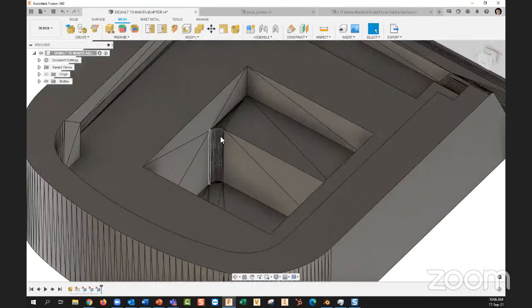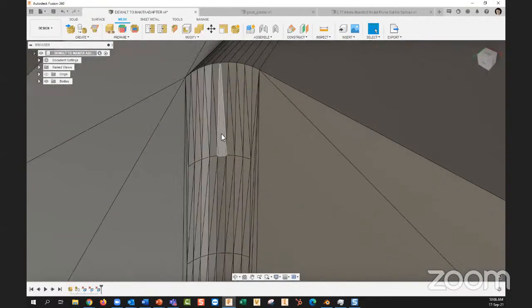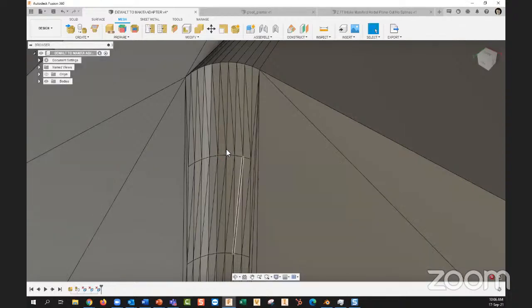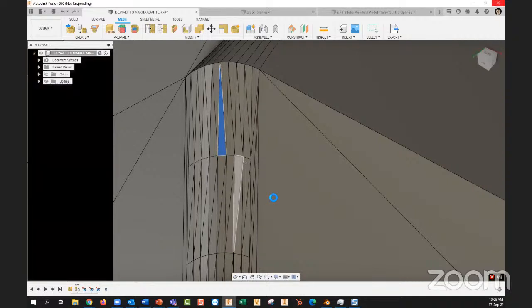But notice you can't get things like this fillet here. Like if you start trying to delete this corner, it's not going to repair as smoothly as you might think. And I already started to make it lag there. And as you can see, I tried deleting that face. It didn't quite work out for me. So that's some of the issues you may still run into until today.